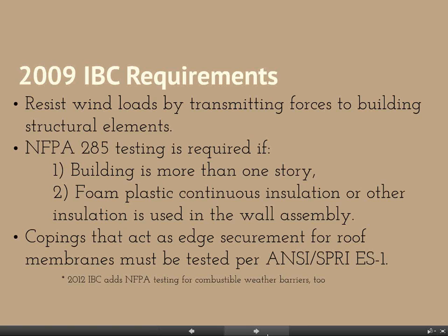The rule of thumb was, before continuous insulation, that you could use the normal panels for buildings up to 40 feet in height, and then above 40 feet you had to go to the fire resistive core. But we'll talk about that in more detail when we get to discussing the cores.